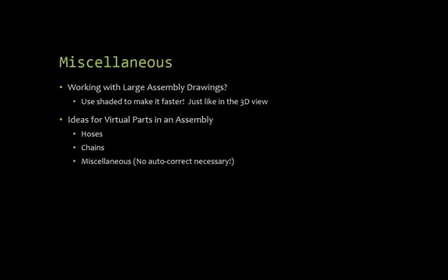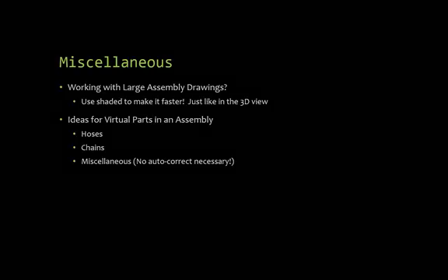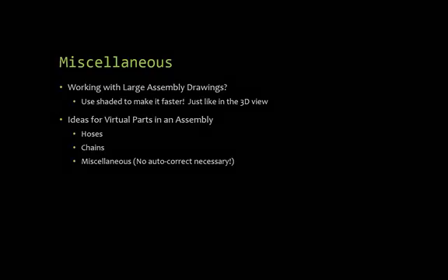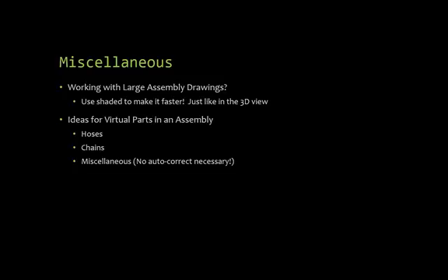All right. So virtual, when I first saw them, I thought it was kind of weird. Like, why would I have a part that doesn't exist in real life? The first time I used it was the virtual assembly, and that's what I was talking to you guys about earlier. I might have an assembly that's all put together, or a bunch of pieces put together. I would pick them all, create a virtual assembly, copy the virtual assembly, dissolve all the assemblies, and that's where I was transferring a lot of my mates over and stuff like that.